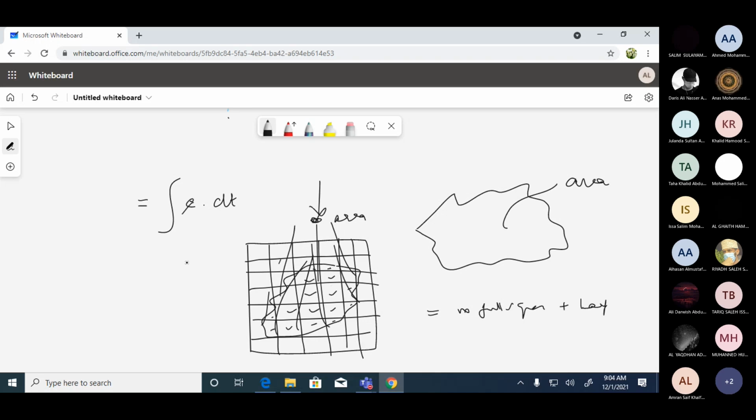So why are we talking about an integral controller? Because the controller will go on calculating the output until the error becomes equal to 0. Integration is continuing the summation until nothing remains. Same way here, to find the output of the integral controller, you multiply the integral gain by the integration of the error, and this will continue till the error becomes equal to 0.